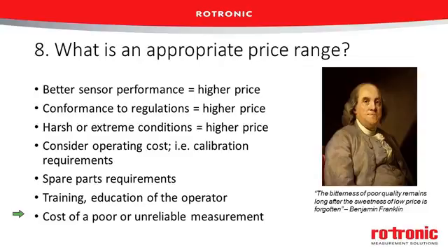So the little transmitter on the wall is telling the humidifier, hey, our room with all of our expensive art is at 0%. We need more humidity. Send me humidity. And sure enough, the humidifier fired up and flooded that room with humidity, and they got severe condensation, of course, and it ruined all that priceless art. In that case, the $500 they spent for the transmitter was nothing compared to that loss. And when you're thinking about price range, again, if it's critical application, critical products, or a very harsh environment, certainly be willing to pay more.